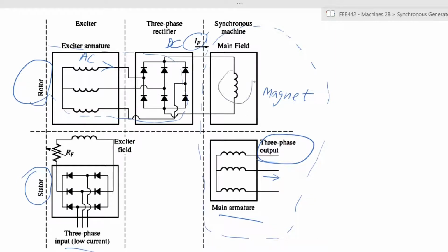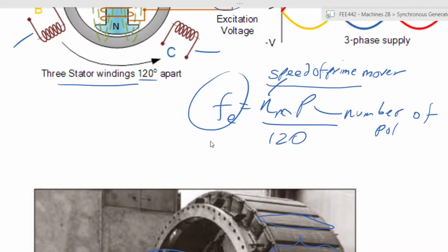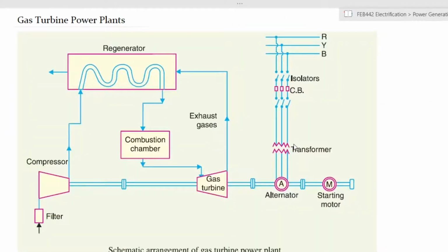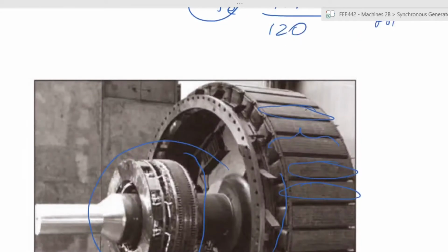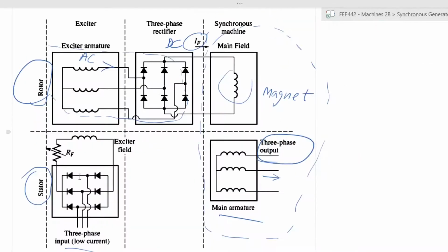So these windings, if we relate it to the photo that we've seen on this side, are the ones that are here. So these are the field windings, and the exciter here, the rest of this circuit that you're seeing on this part, right? So the main field windings are the many poles that you saw in the diagram, and the exciter is mounted on the same shaft as the rotor. So the rectifier and the smaller windings that are supplied are mounted on there.